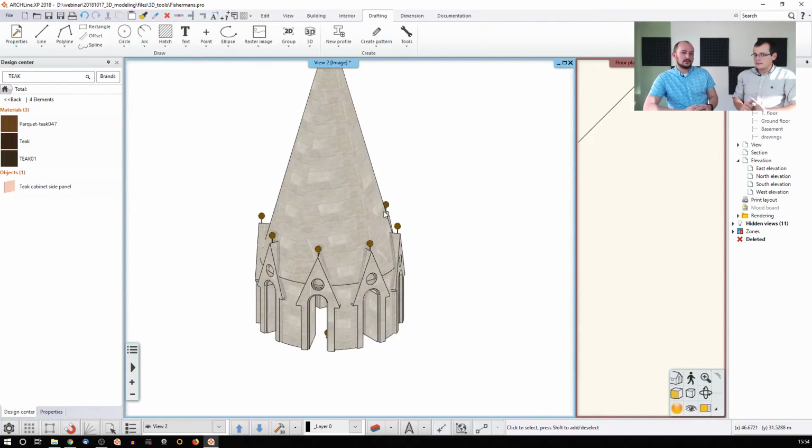Actually, that's what I'm also teaching. When you see something that you would like to model, perhaps this panel behind us or anything, you need to look at it from an analytical point of view, trying to determine what are the smallest kind of atoms or shapes that you can already define with your existing knowledge, and then based upon that knowledge you just design the parts and then align them together and make something larger. So for example, in this case, we only used 2 tools, the revolve and the push-pull, and based on those tools we could create such a complex thing.